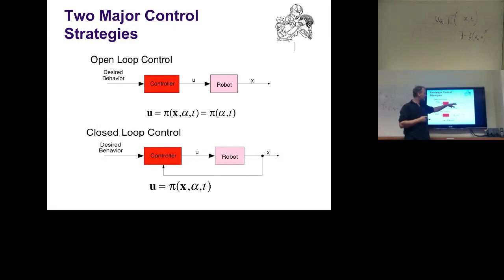And if you have delays, for instance, using a feed-forward command in order to do a fast movement and only turn on feedback control when you are close and slower moving is often the right thing to do. So that's what we often do. Like here's a pen, I want to grasp it. My initial approach, my fast approach to the pen was most of the time open loop. But then when I start touching it and get feedback, then I go into a feedback scenario.